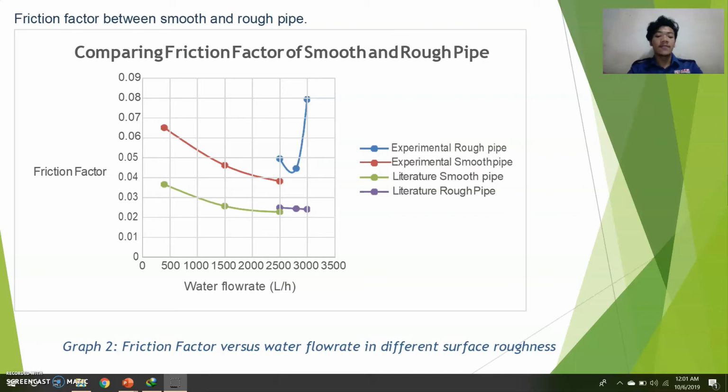However, for a real flow in a pipe, there is an energy loss as a consequence of the viscous dissipation and shear stress of friction that occurs throughout the fluid in the pipe. Therefore, Bernoulli's principle of conservation of energy is not suitable to calculate the flow rate and the friction factor. The most suitable way is to use the energy equation, which includes the friction and the loss in energy.